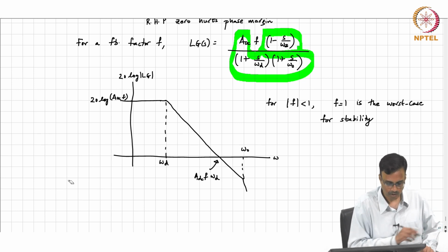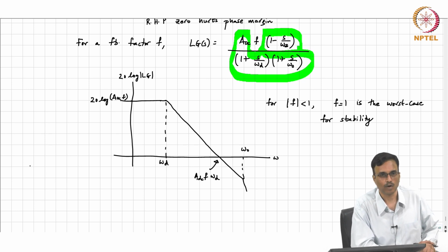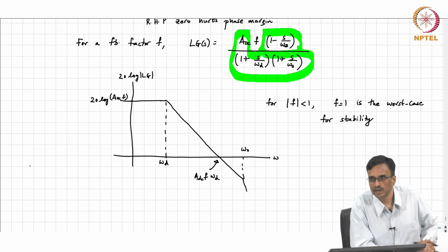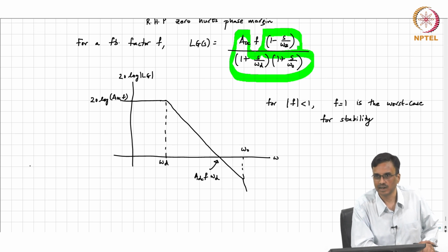Like standing on top of a building, it's a trade off: how confident you are, and how close you want to go to the wall. If you like to play things very conservatively, then you will shoot for a very large phase margin and lose bandwidth. If you like to live life on the edge, you will say, okay, I'll have a 15-degree phase margin, and now I get oodles of bandwidth, but now I'm a lot more sensitive to everything.